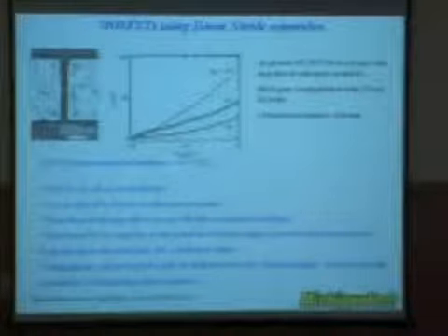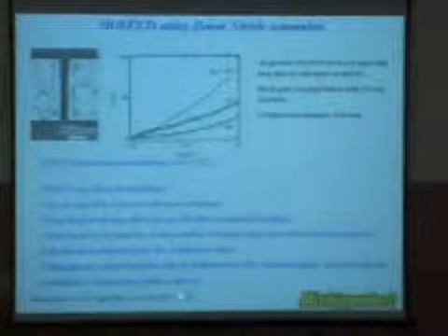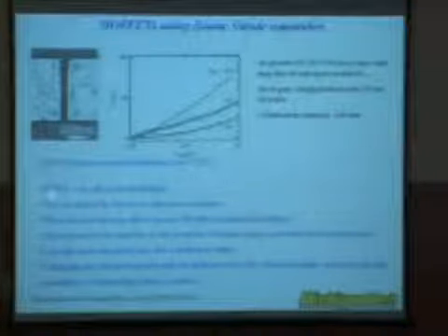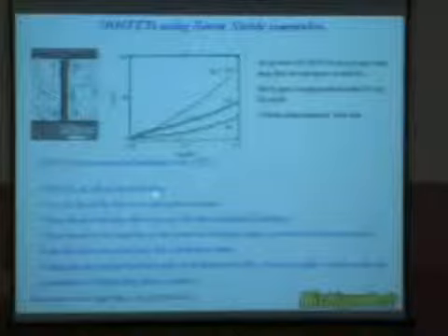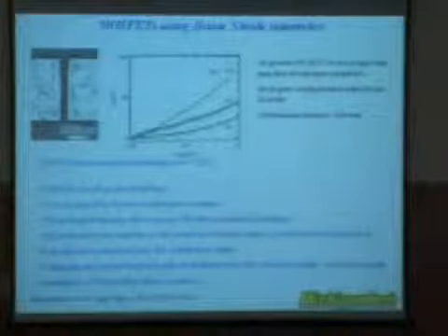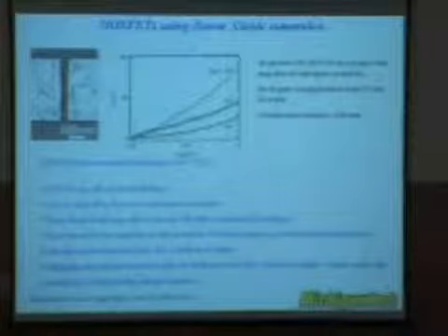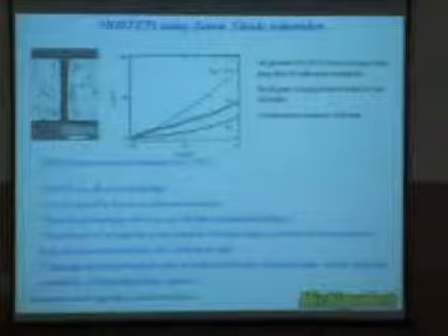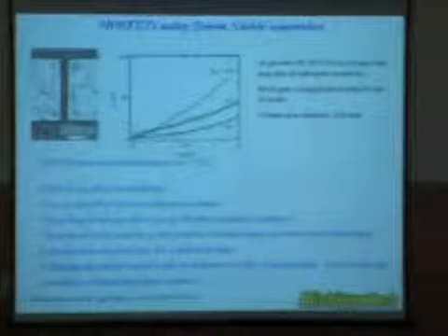All right, actually a device, a field effect transistor, using boron nitride nanotubes was already demonstrated by the IBM group back in 2003. Some of the advantages here are that boron nitride nanotubes are always semiconducting. They can be doped by boron or nitrogen. So you don't have to find a dopant for boron nitride nanotubes. You just take some of the boron away or take some of the nitrogen away, then you can form P and N types.